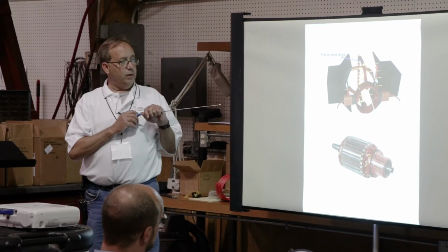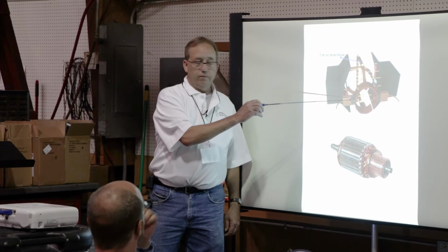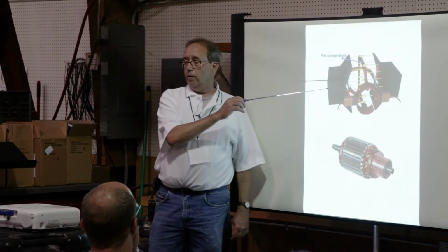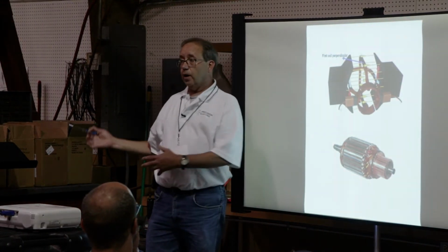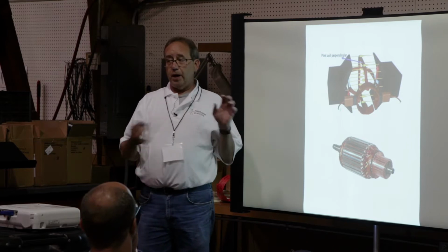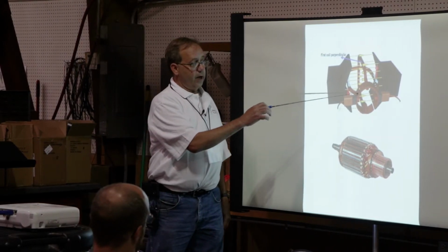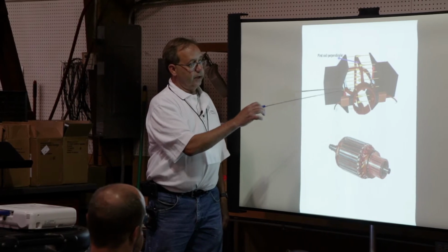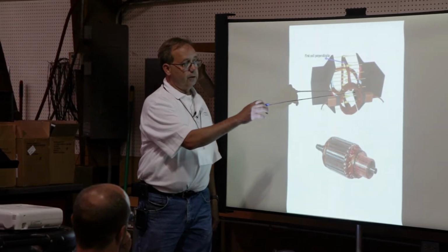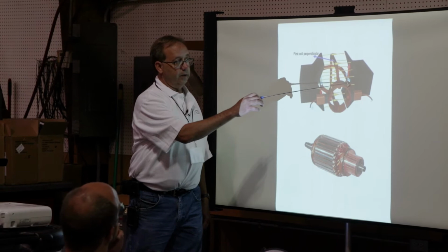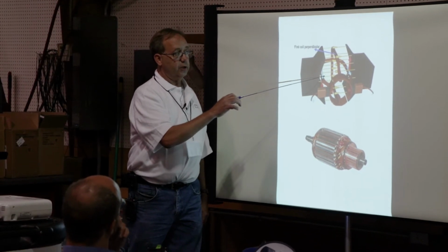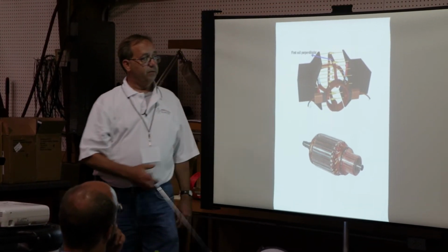That is the primary moment for us to apply voltage to that coil from our drive. So when we power up this armature, we're going to have this commutator segment connected to the coil that is in perpendicular position to the pole pieces.